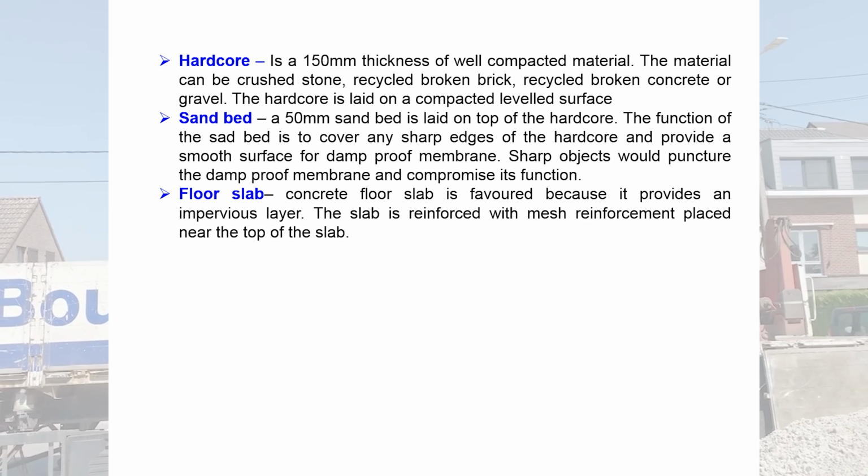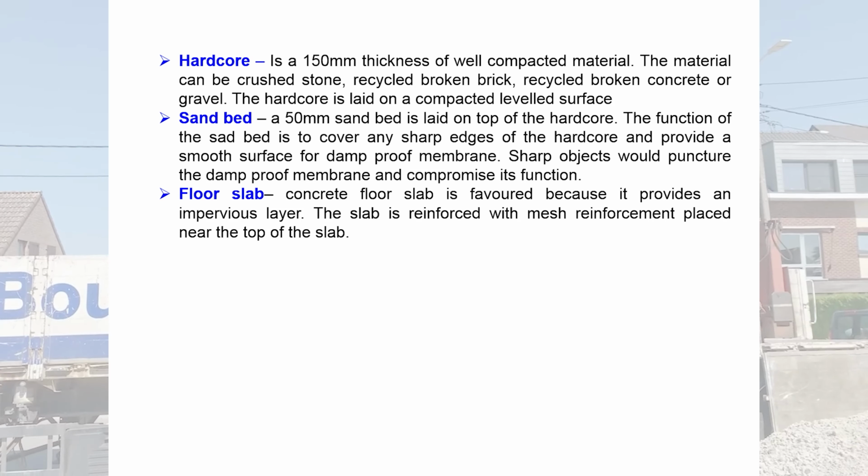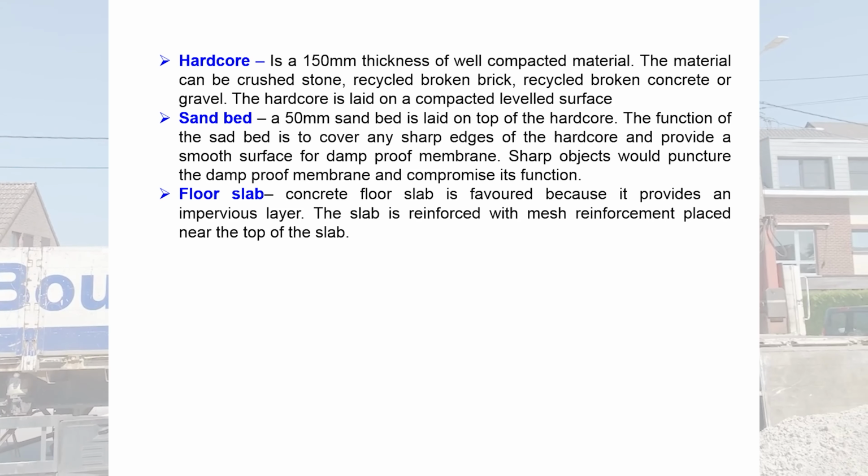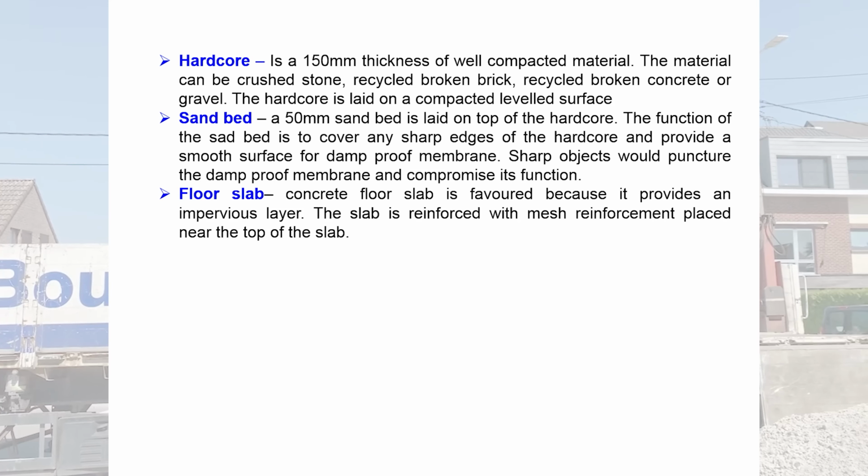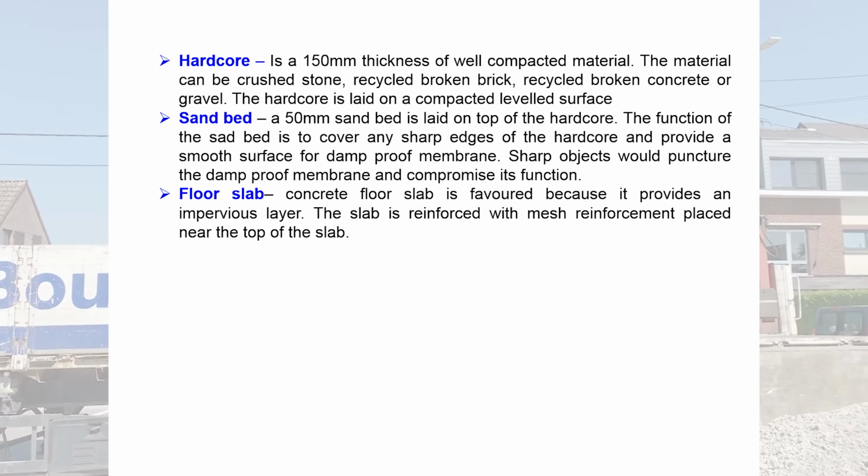Floor slab. Concrete floor slab is favored because it provides an impervious layer. The slab is reinforced with mesh reinforcement placed near the top of the slab.